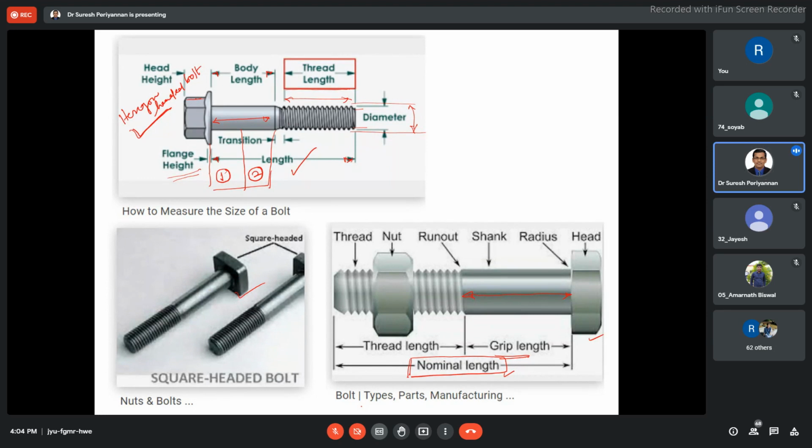The parts are assembled by means of a spanner. The length of the spanner is large compared to the radius of the thread. You might have seen this, because the mechanical advantage is more, and the force required to tighten the joint is small.